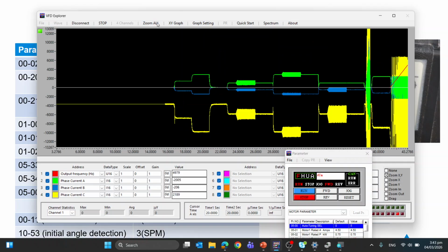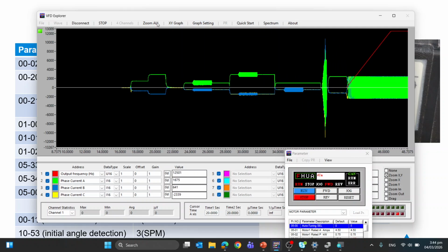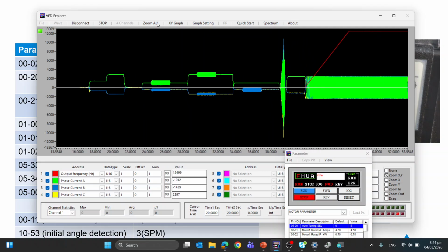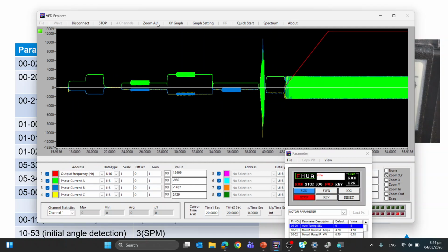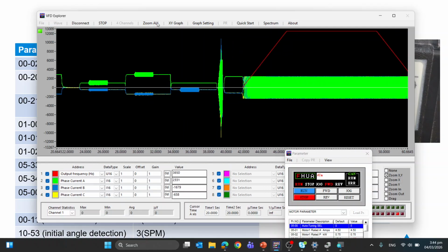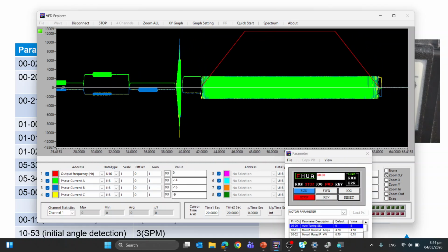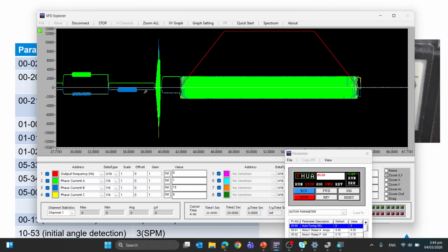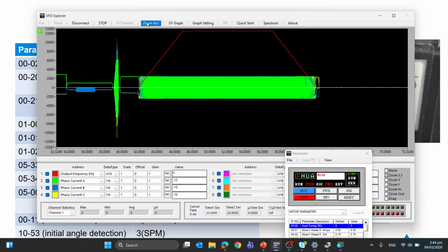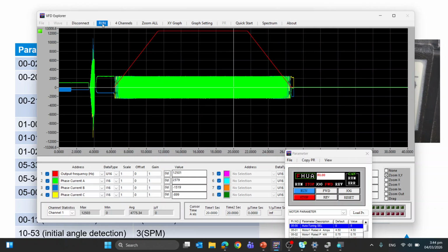Now, one thing I want to mention is the graph is only limited to 40 seconds. So if you want to do data logging, this one cannot. It's just for debugging and tuning the motor. Okay, we have completed the setup. It's for finding the resistance, finding the inductance of the motor, and then doing the running test operation. Okay, then I click stop. It will stop the graph.